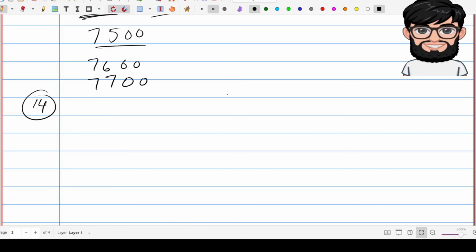The initial call should be made about 15 miles from the airport. This is a generic one; you should remember that 15 miles is when you should make the communication with ATC.